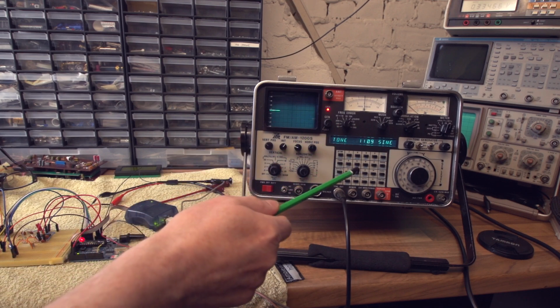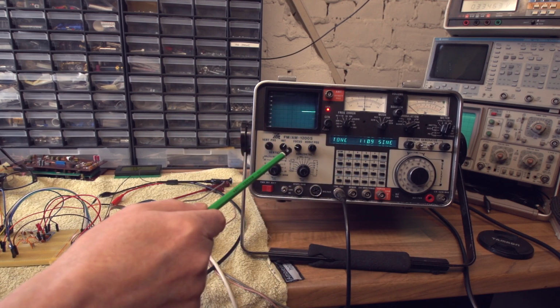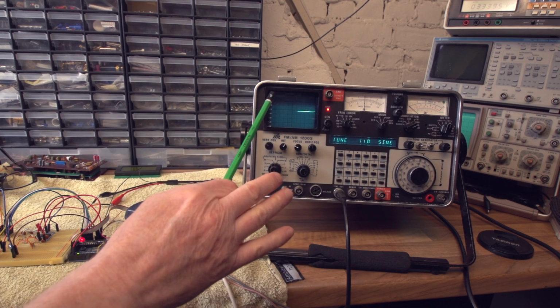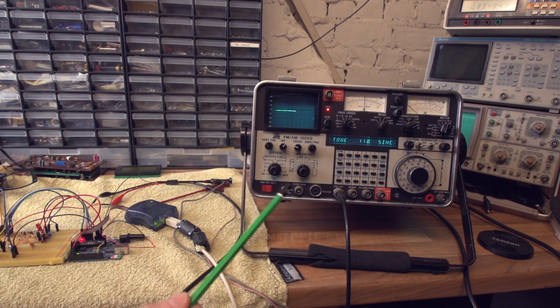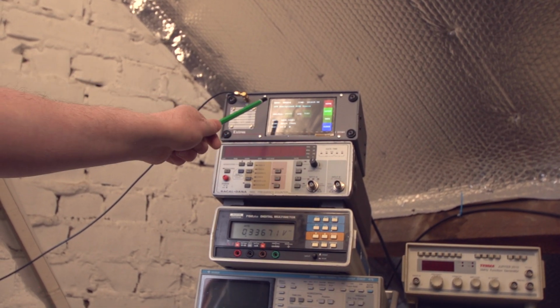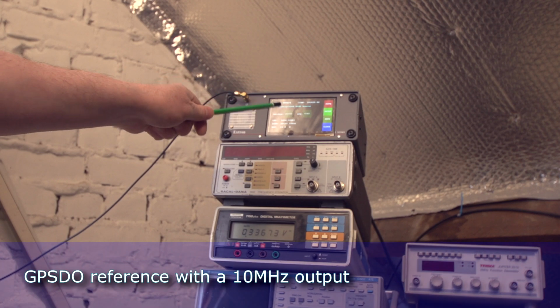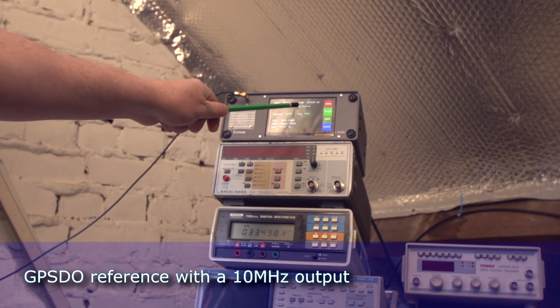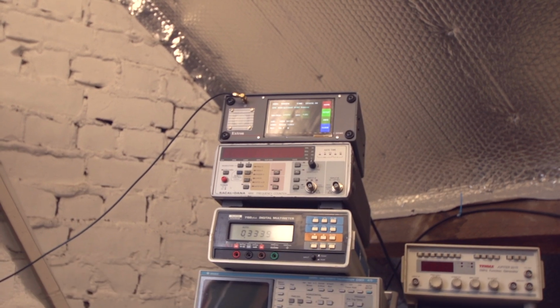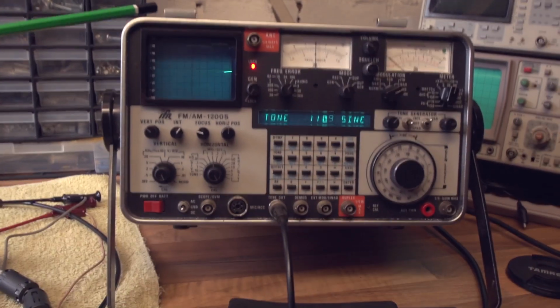This in turn has a very accurate internal crystal oscillator oven. It's actually very good as a standalone reference, but just to be doubly sure, I am driving it from our GPSDO. It's completely locked. That's given us a very precise 10 megahertz reference signal, and that signal's coming here to drive the IFR.